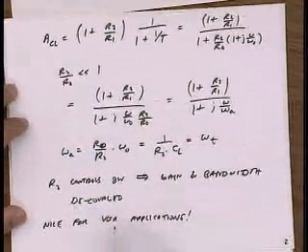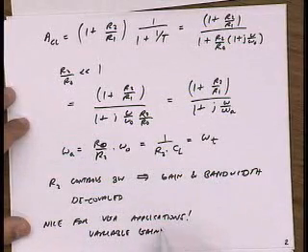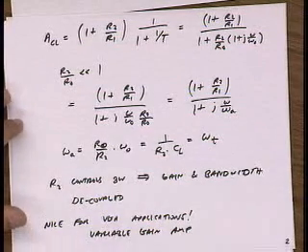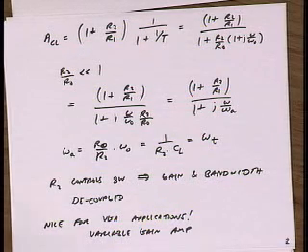Because in a VGA or a variable gain amplifier, we're varying the gain all the time, right? The amplifier might be in a feedback loop. And now if the bandwidth is constant, that means I can stabilize my loop with just one bandwidth setting, right? I know that the bandwidth is not going to vary considerably in different gain settings, and so now in my feedback loop, I just have to worry about one pole. I don't have to worry about that pole moving around.